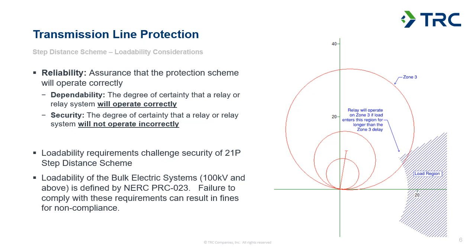So we're going to take a look at some of the other considerations that go into our transmission line protection. I want to talk first about loadability considerations. Loadability is really just that we want our protection to be able to operate for all fault cases. But ideally, if we're in a scenario where we're in a heavily loaded part of the system and there's a reason why the system operators are having to push the limits based on other outages or other considerations,